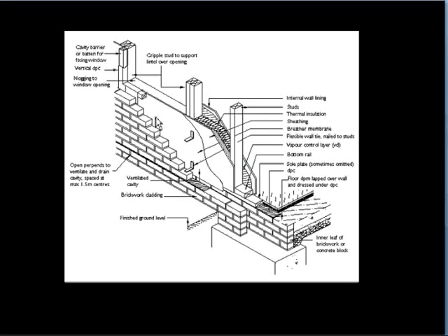In terms of internal decay, that's prevented by having a vapour barrier, and the vapour barrier here is on the inside of the construction, just inside the plasterboard finish, and that prevents any water vapour from inside the space transferring across and condensing on the colder plywood surface.